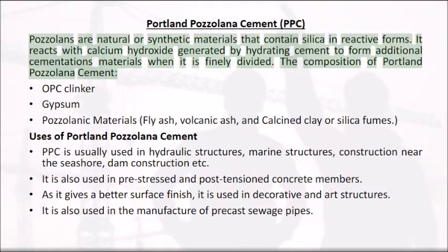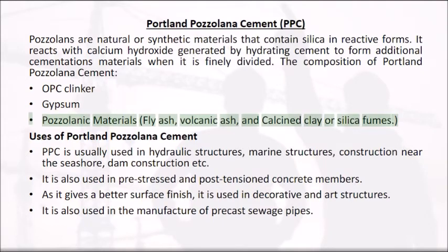The composition of Portland Pozzolana cement: OPC clinker, gypsum, and pozzolanic materials such as fly ash, volcanic ash, calcined clay, or silica fumes.